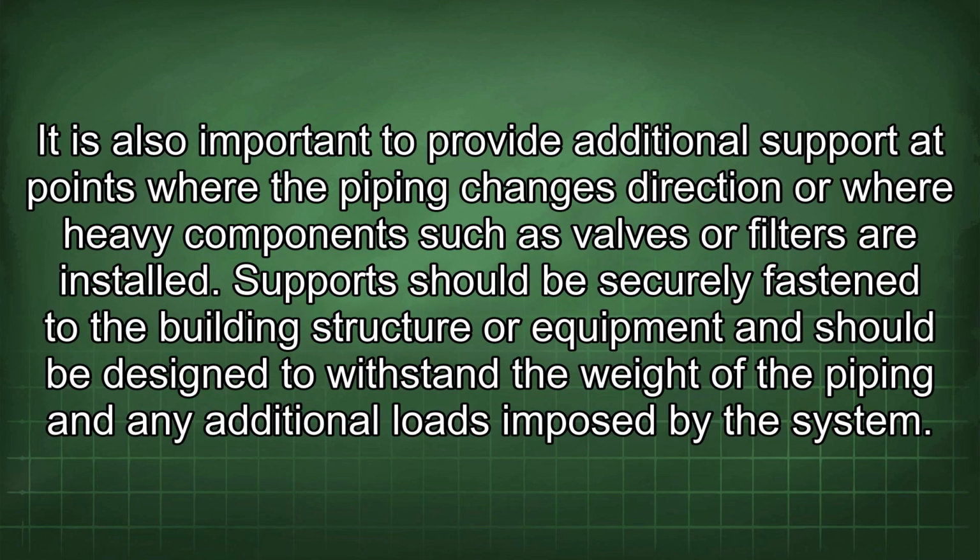It is also important to provide additional support at points where the piping changes direction or where heavy components such as valves or filters are installed. Support should be securely fastened to the building structure or equipment and should be designed to withstand the weight of the piping and any additional loads imposed by the system.